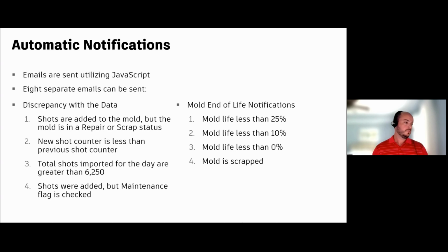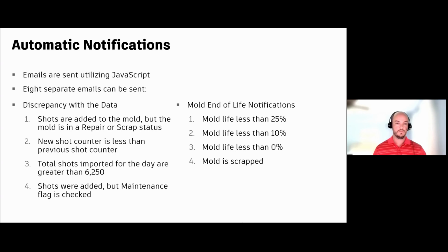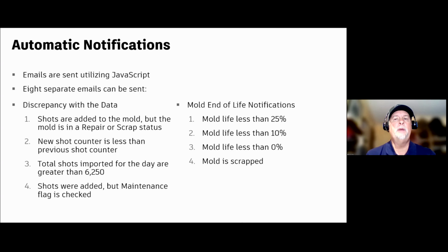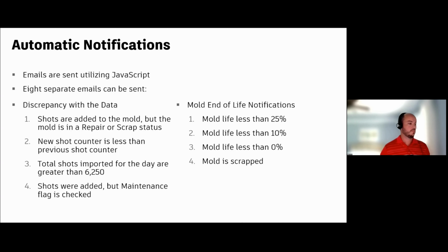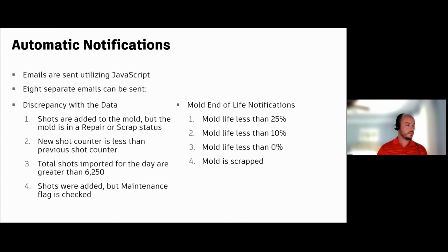We also want to make sure that the shot count is not less than the shot count of yesterday. The shot counts are given to us by a human person reading an actual odometer that is mechanically affixed to the side of the mold. Every time the mold opens and closes, that mechanical odometer calculates an additional new number, and it's very easy for them to misread that. So we're making sure there that we're getting an accurate number from them.